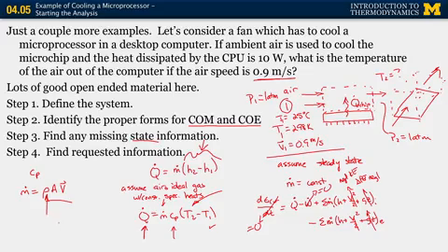instead we say, hey, wait, we're smart enough to know that the ideal gas law says that the pressure of the gas is equal to the product of the density times the specific gas constant times the temperature. This is the specific gas constant. Recall that the specific gas constant is related to the universal gas constant through the molecular weight. So we know that R for air, the specific gas constant, is equal to the universal gas constant divided by the molecular weight of